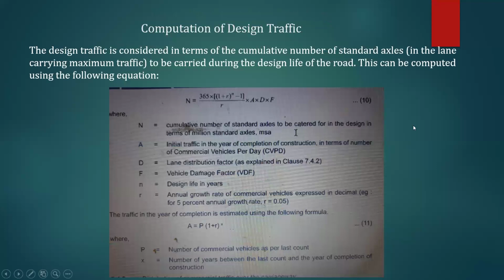And other than that, the traffic will be varying. In pavement design we always use the traffic growth rate factor. Basically the traffic will not be the same. Maybe the pavement was designed for 100 MSA, but now the traffic is 200 MSA. To take into consideration that additional 100 MSA, what overlay you have to lay is very much important. You know this fundamental equation, I need not explain much. Most of the people know this equation from IRC 37 2001 itself.